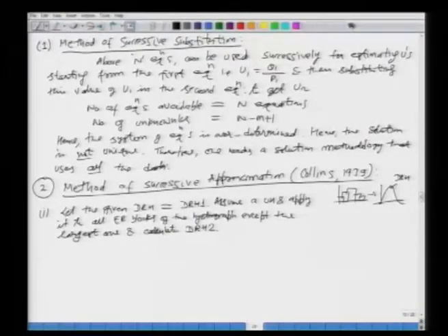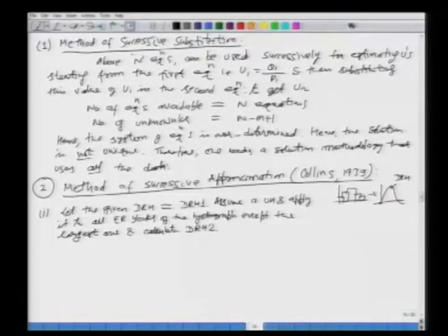So, what we are doing is, we are saying that the given DRH is DRH 1, and then we calculate the direct runoff hydrograph response from the catchment from the effective rainfall hyetograph, the whole except the largest one. If you look here, which is the largest one? This one. So, you calculate the DRH from all the effective rainfalls, this one, this one, this one and this one except this one. You calculate the DRH and let us call that DRH 2.